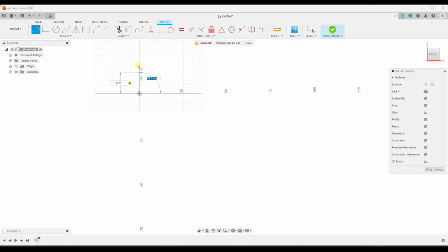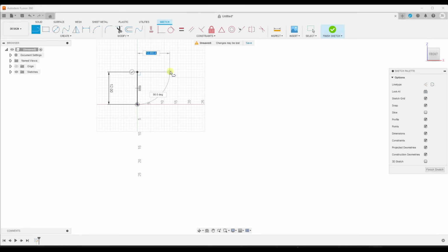Now, one thing that you could do, by the way, is if you want to type in an angle, you can tab and then type in a value like this, right? So notice how this gives me 180 degrees. I actually don't want that, but you can use that tab key. You can do a tab or a shift tab in order to tab back and forth between these boxes. And in this case, I just want to click right here to set that length to 12 inches, right? And so now we've got a 12-inch height.